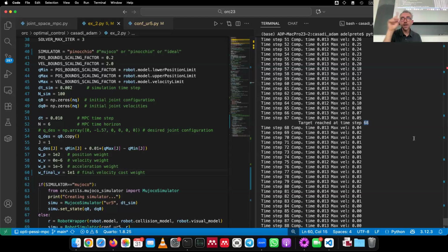The solution is going to be a cyclic trajectory, one you can cycle on forever. So that trajectory is a control invariant set. It's a very thin one because it's just a trajectory, so it's probably not an improvement over the one we are using here, which is just zero velocities. But if this cyclic trajectory is close to the trajectory that your system should be following during the motion, then it's fine.